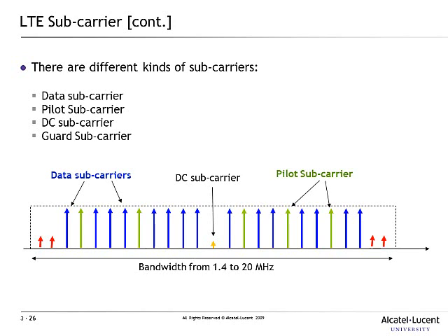You also need something called a DC subcarrier, which is used to initially synchronize and to know the centermost frequency in the band, because we have so many different bands in which it can operate. So the DC subcarrier is used by the mobile device to locate the center of the OFDM frequency band.